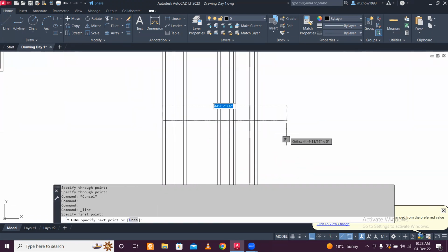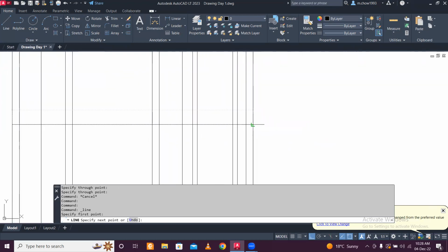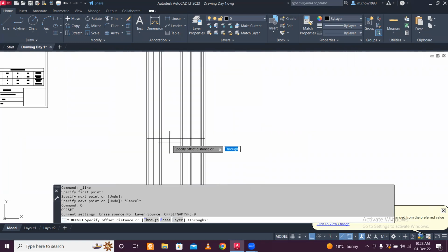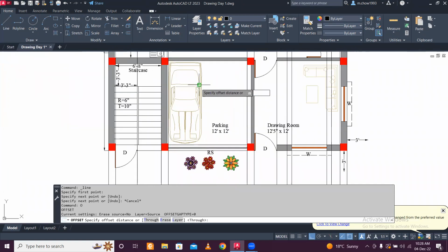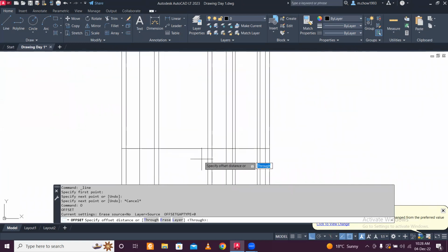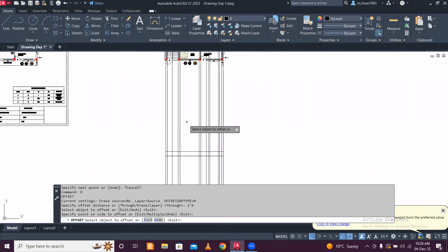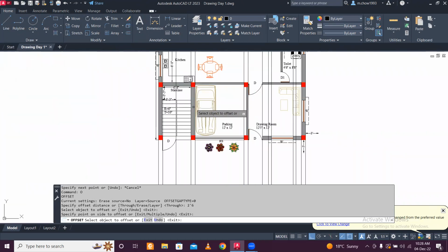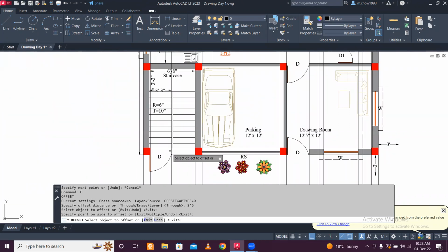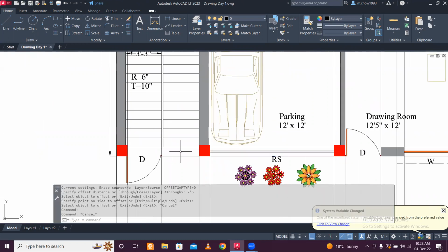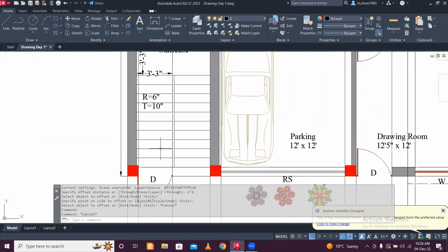Let's move forward and make the just work. So we'll draw a line here. This will be our ground floor level. Okay, sorry, down level, and plinth height. We'll take plinth height of 2 feet 6 inches. Okay, so 2 feet 6 inches offset we take from this line. So this is the plinth level, and now you can see here we have a number of steps. You can see, we have this 1, 2, 3.